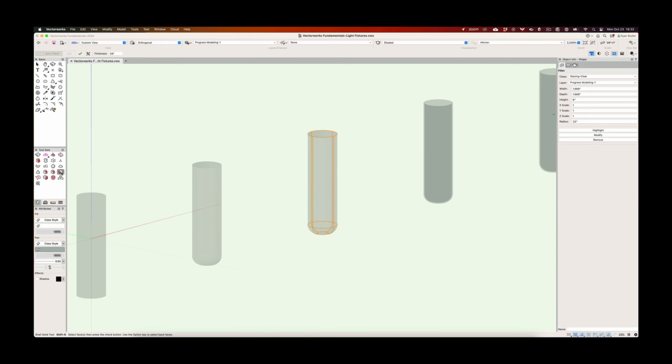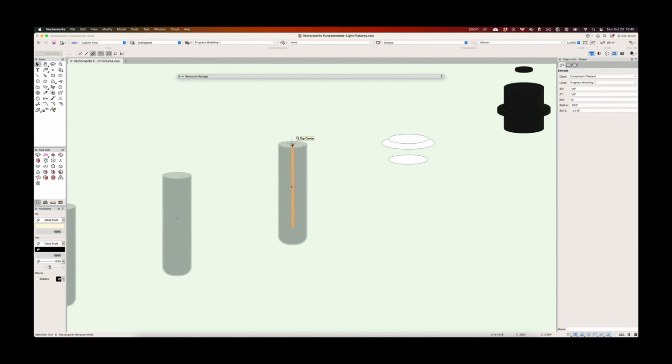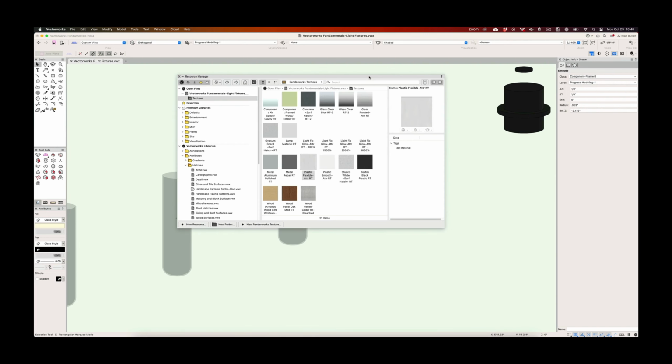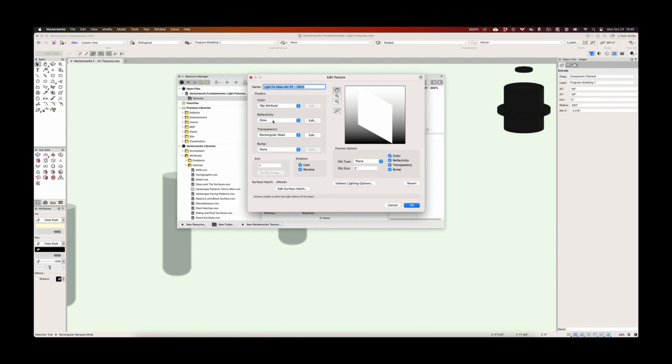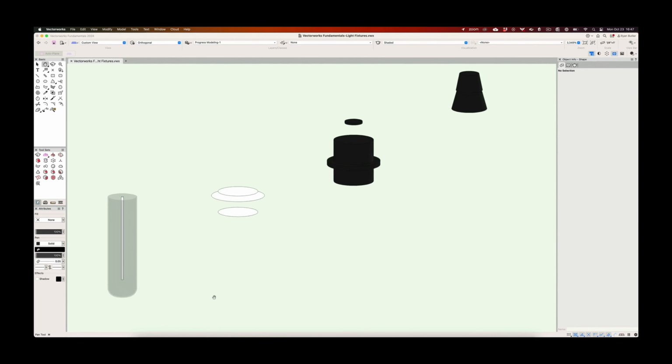To make the shape hollow, the shell solid tool is the way to do it. Select the tool and set the desired thickness, then select the face of the shape you want to have an open edge. To model the filament, it's another extruded circle, but this time the extrusion has its own filament class. In that class, a glow texture is used. More on that later.